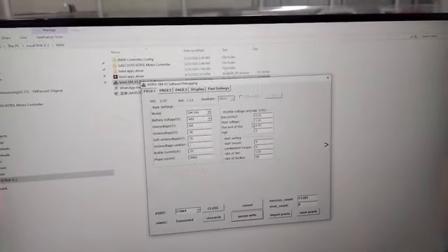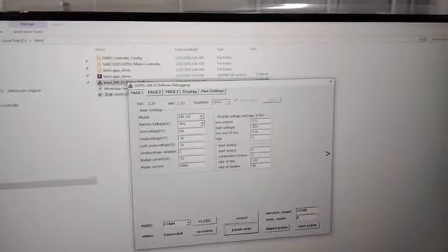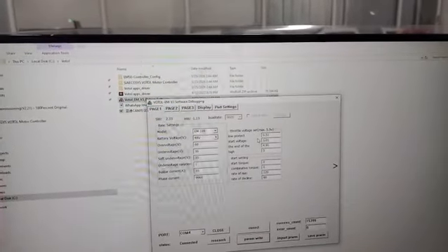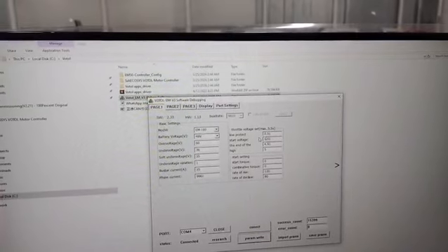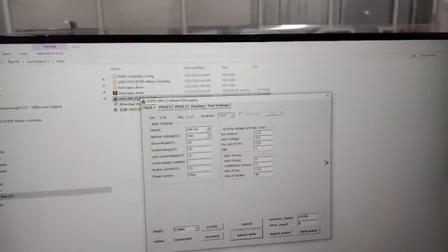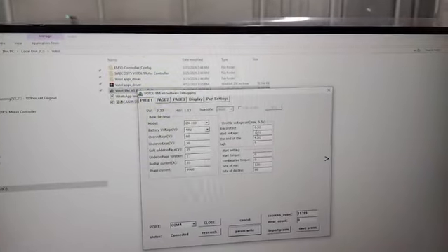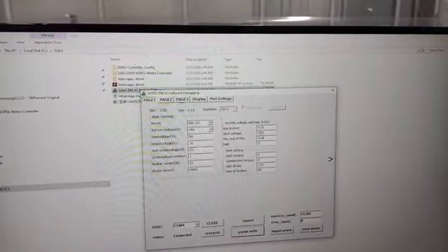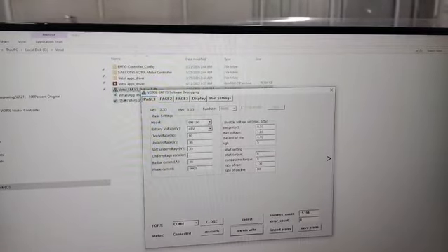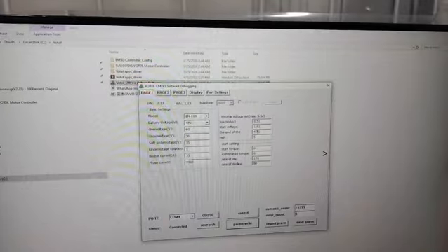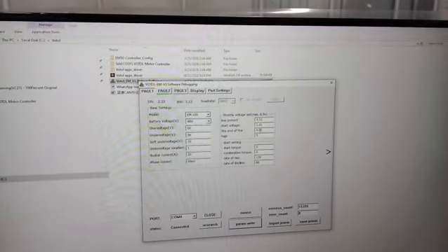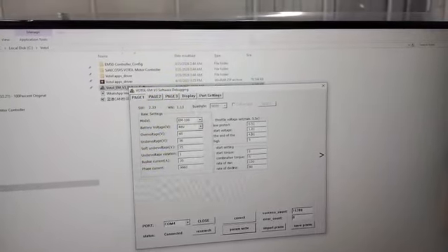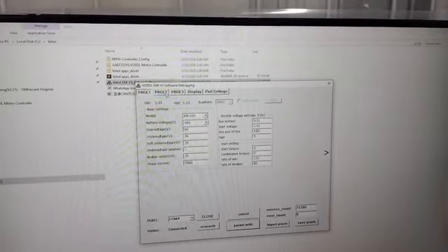So basically there is a buffer. So we have the start voltage up from 1%. We have to take the throttle from 1 volt to 4 volt. Here is not an accurate voltage we have to give. So from 0 to 5 we have to make some buffer. So here is 1 volt for the lower voltage, 4 volt for the end voltage, or maybe we say high voltage. So this is the throttle setting.